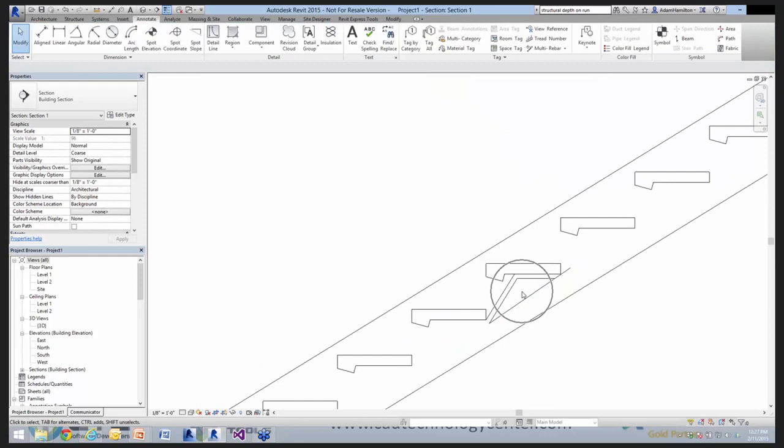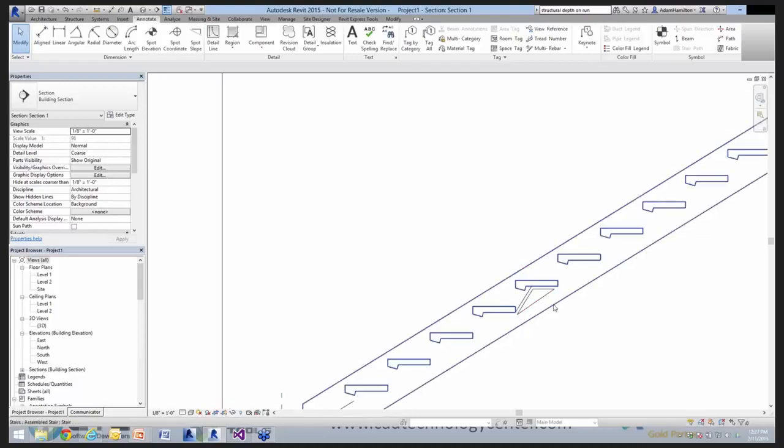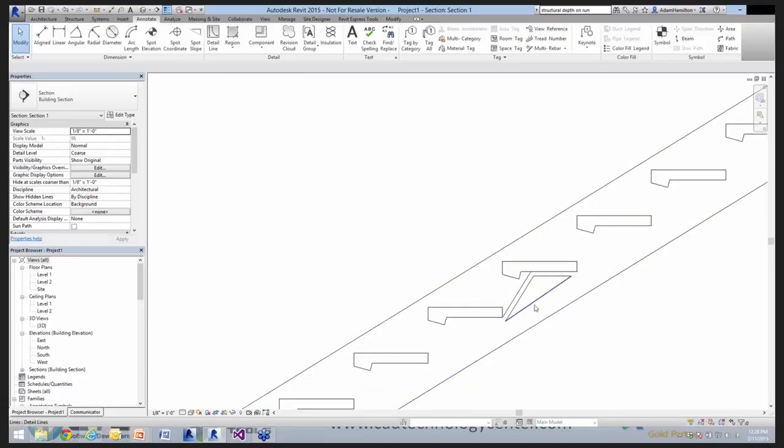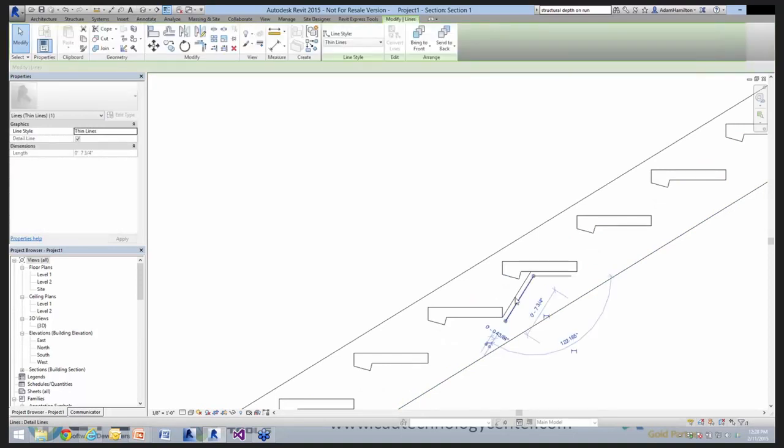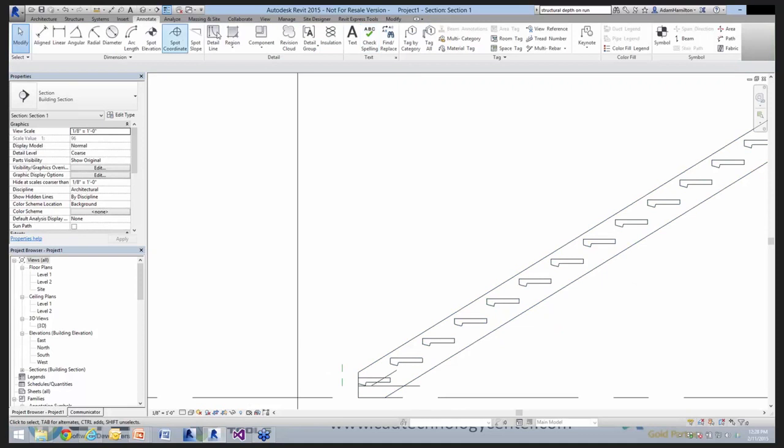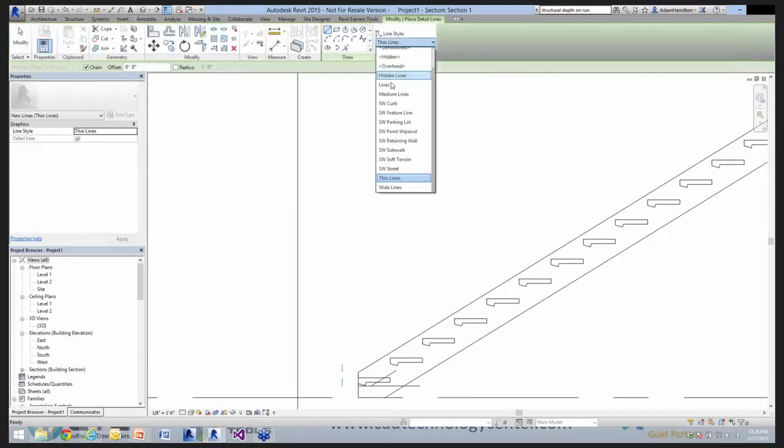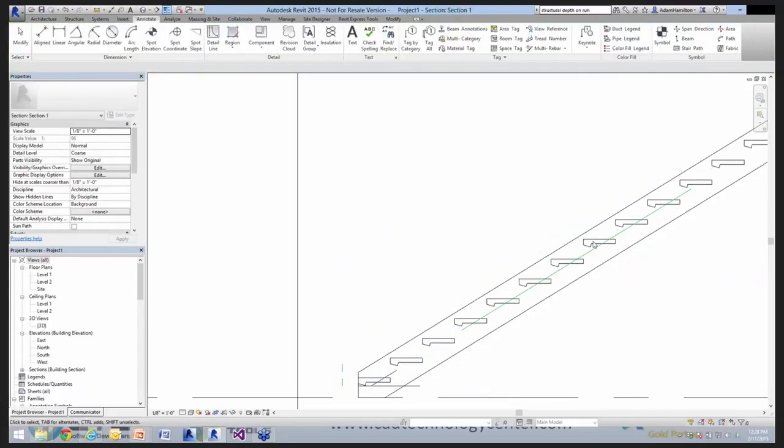Now Revit doesn't have the ability to cut the profile of a support in this direction. Okay, treads and risers and nosings run the width of the stair, but when we talk about how the supports are run, they run perpendicular from bottom to top, and so they're extruded along the length of the stair, say this path, this direction, and so you can't cut that way.